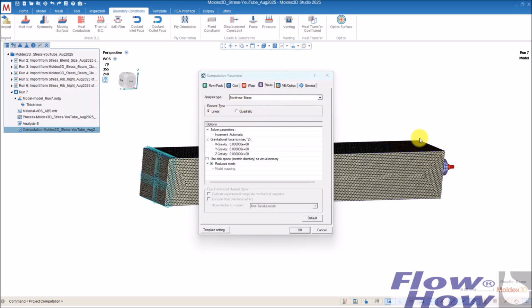Then, for example, if you have chosen too big a load out here, if you don't have the nonlinear, the load will not follow as a normal to the surface during the bending. I will show that later. But normally I would say go for these two if you have bigger deformations.